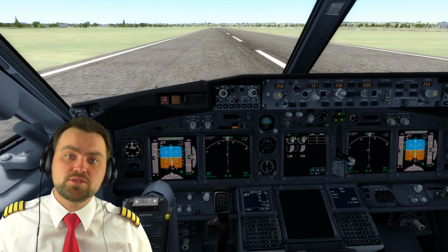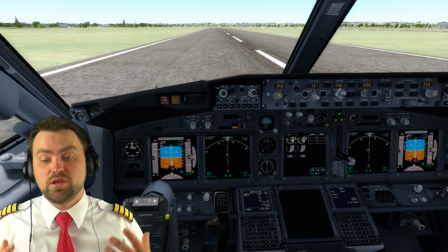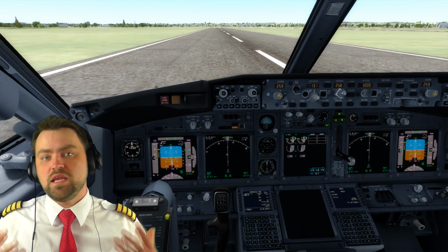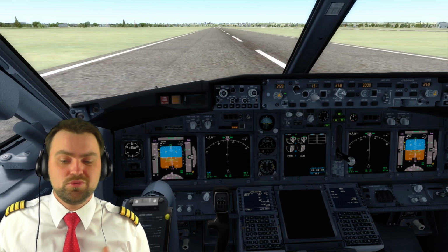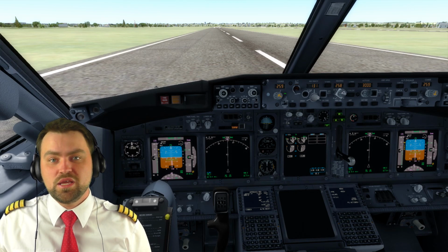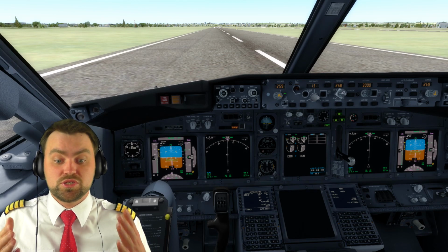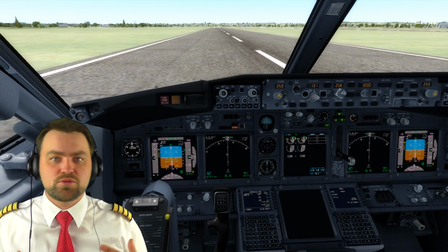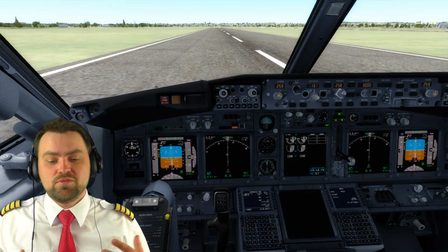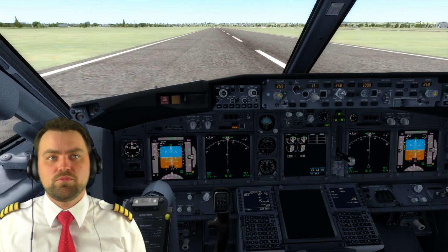As you saw, my friends, most of the time I use LNAV, VNAV, which takes data from your flight management computer, so you don't really need to do many of the stuff. We just extend the flaps and we just intercepted the localizer from LNAV and glide slope from VNAV mode, which is not usual picture for me.